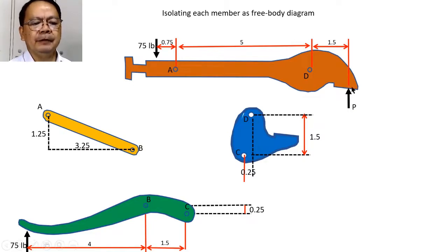And this P is also the same force as acting here, kasi yung konsepto ng action-reaction forces, they are opposite in direction and equal in magnitude. Kaya kung may force na nag-act dito, somewhere here, yung bola na tinanggal natin dito sa babang bahagi ng vice grip, dapat meron ding force and the direction of the force is downward. And the magnitude is also equal to P.